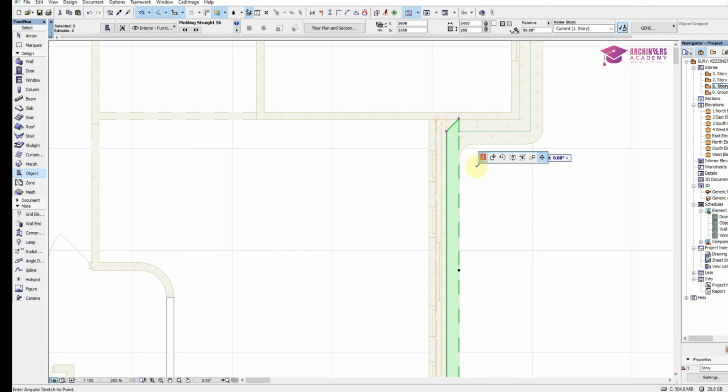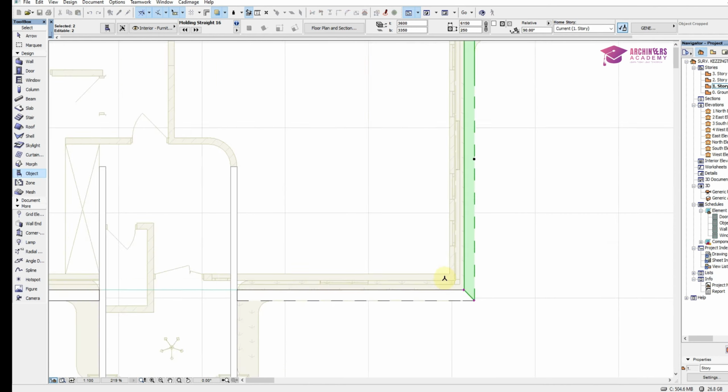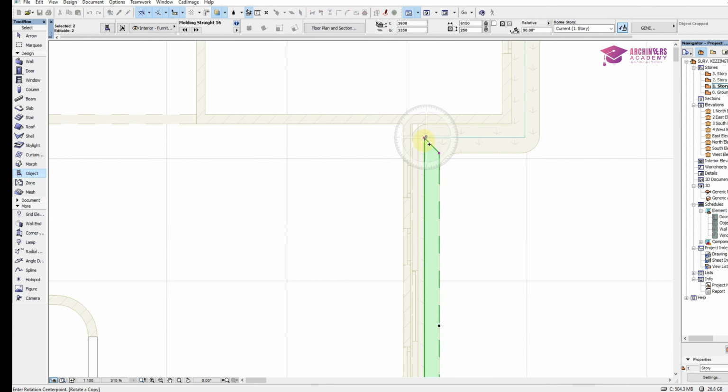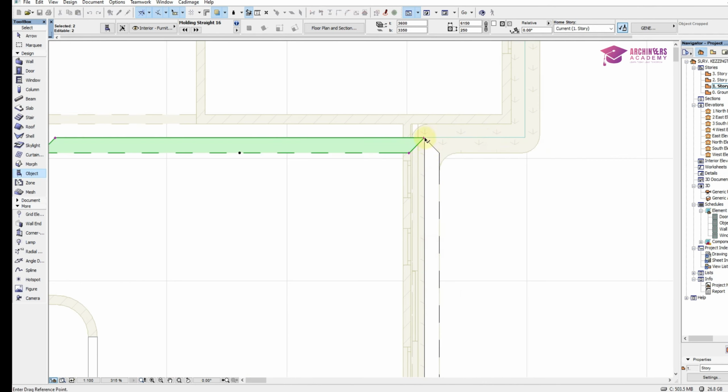This black bullet over here is always outside, not inside. That shows that you're not putting your concrete fascia wrongly. So Control Shift E. Ensure that I rotate it in a way that the black bullet is always outside.